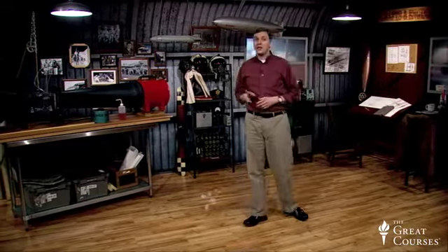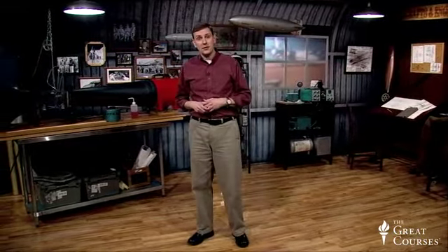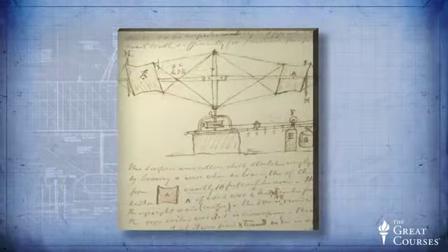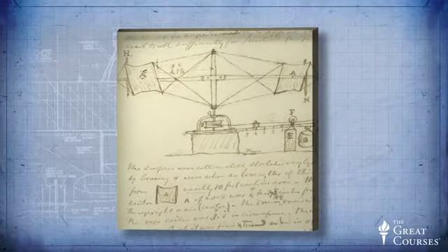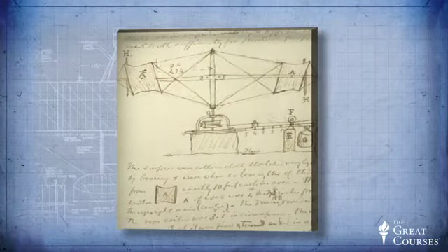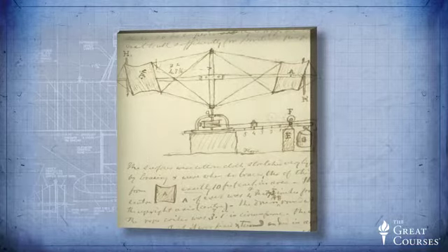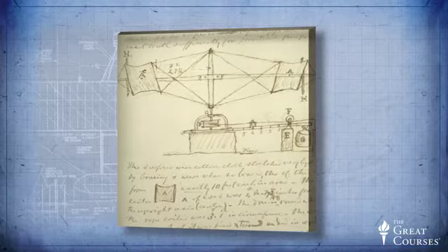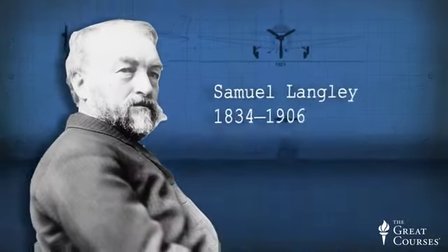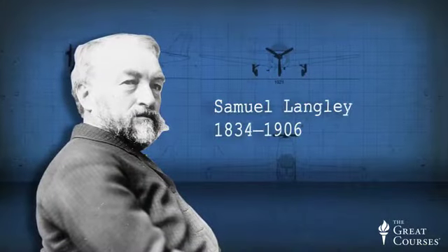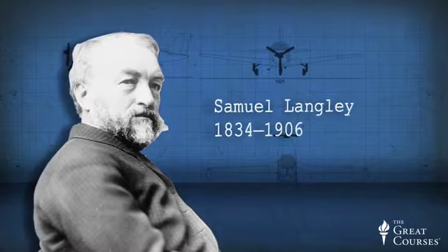So from the early days of aeronautical engineering, careful experimentation has been a hallmark of engineering practice. The earliest attempts at creating experimental facilities for aerodynamic testing were focused on the development of a whirling arm. It was relatively straightforward to mount a model on a whirling arm, spin it around, and measure the amount of lift. In many cases, the technique was to indirectly measure the amount of deflection of the arm in the vertical direction. For example, Samuel Langley was one of the first experimentalists to develop such devices in the late 1800s.